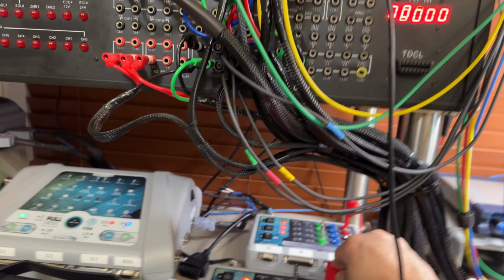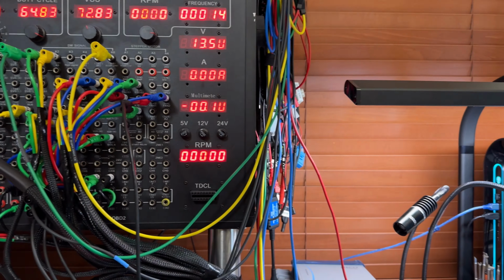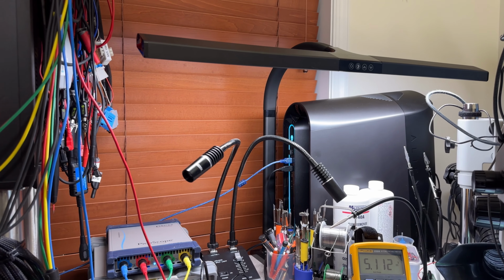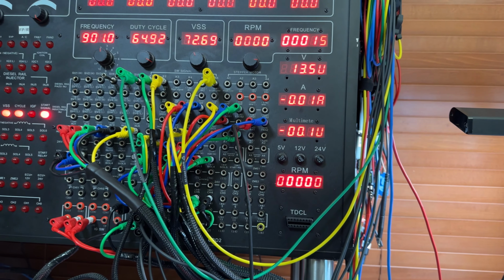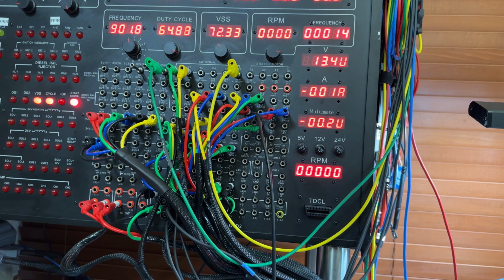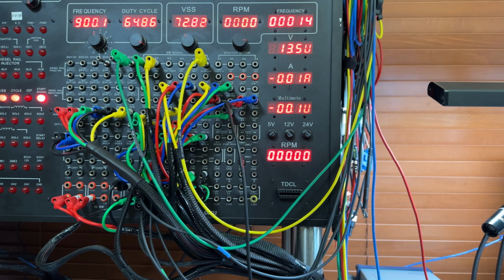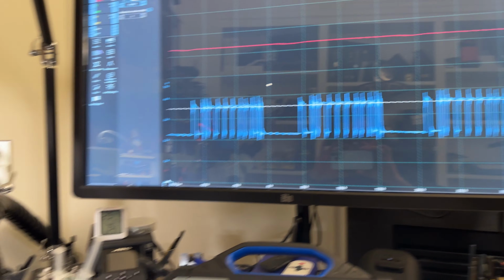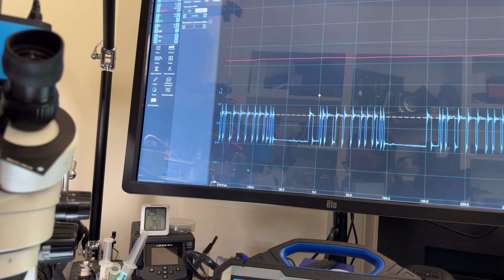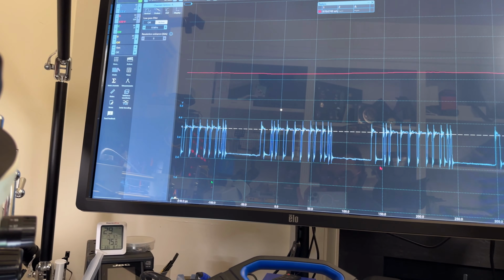So this driver uses a smaller output. I've got to be careful with the Nissans. That's something that I'm going to mark in here. Even though I tested, I'm not sure if I recorded that in the first video, and it wasn't able to turn the fuel pump off. We got a glitch on the CAN network, which was shutting the bus down.